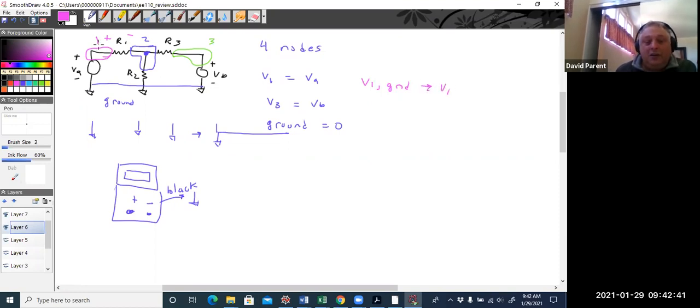So when you see V node 1, that's 1 to ground, 2 to ground, 3 to ground, and you're just no longer saying that. And sometimes people forget that potential is measured between 2 different points, whereas current is through. So current doesn't go across a resistor, it goes through a resistor. Potential doesn't go through a resistor, it falls across, that kind of thing.